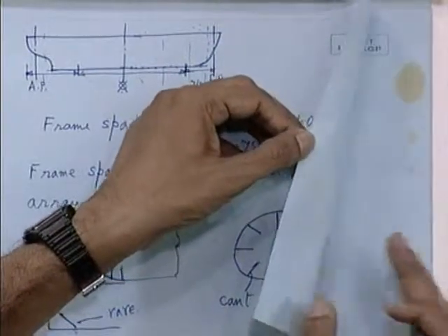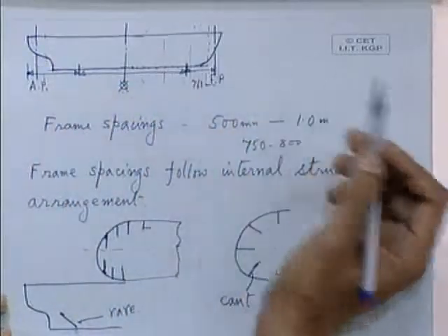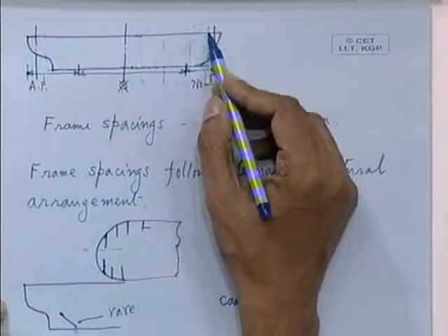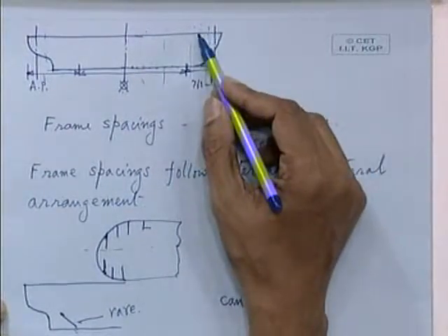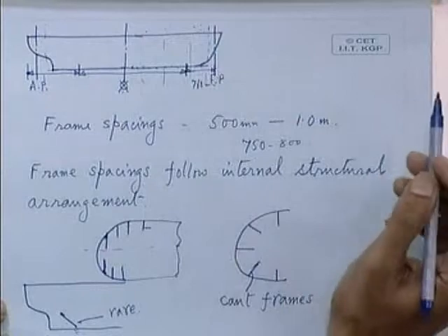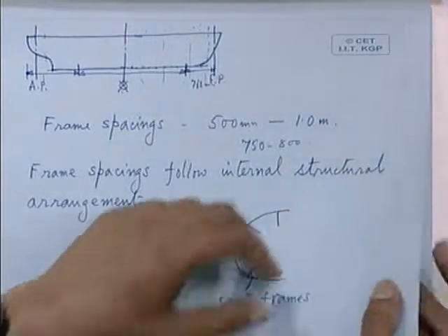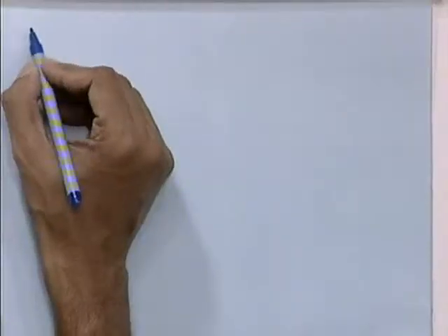So those arrangements in the shipyard itself, or the naval architect who is making the drawing, he has to keep this in mind. Of course, the lines will not be very much altered, that is, the molded lines will be the same, but your framing plan has to show this clearly. So normally after the lines are drawn, for structural arrangement, you make what is called the framing plan.